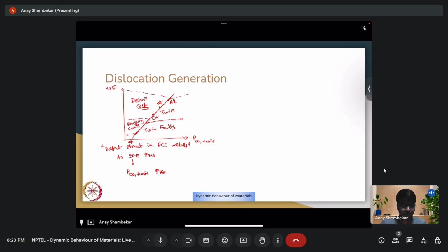Dislocations usually move a short distance at subsonic speeds, and as the shock wave propagates forward, more and more dislocation interfaces are generated. One of the advantages of this homogeneous dislocation generation model proposed by Myers is that it does not require any supersonic dislocations, and it ends up getting us an estimate for dislocation density.